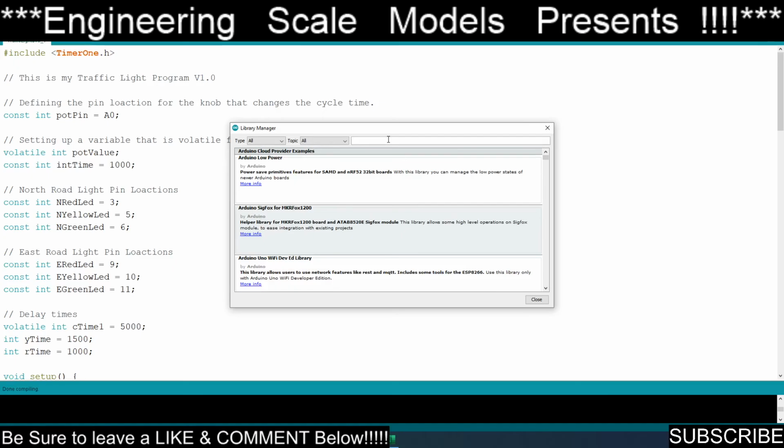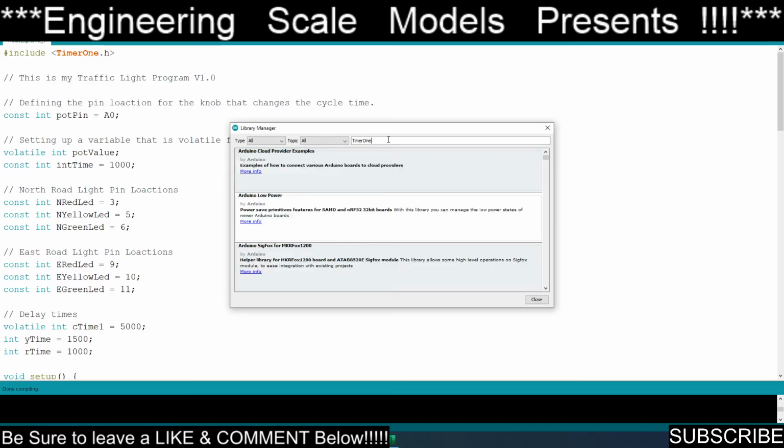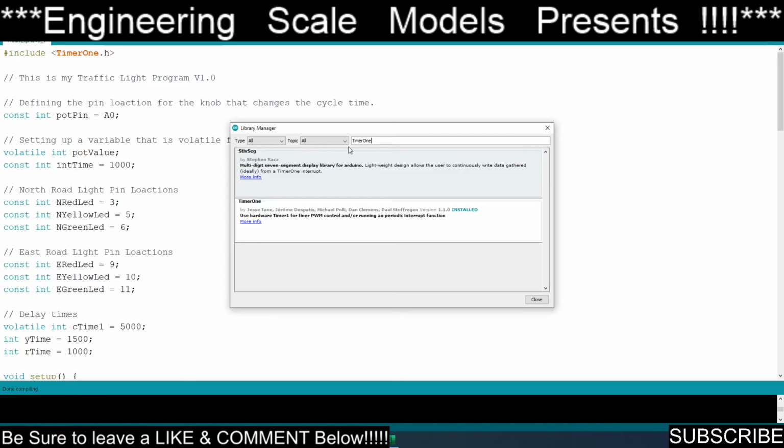It's going to take a minute to load, and you come into the search box and you type in TIMER1 and you hit search, and it gives me 2. I need timer1 because that's the name of it, and then it would tell you you can install it. I already have it installed. So that's how you can get libraries.